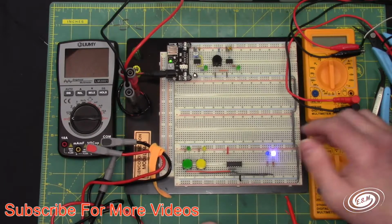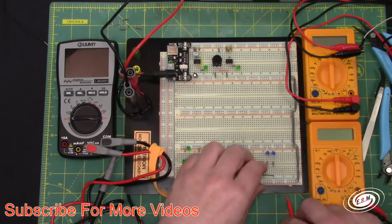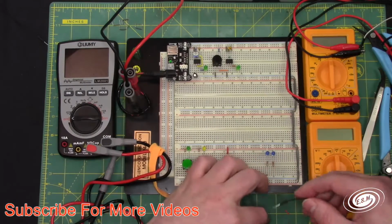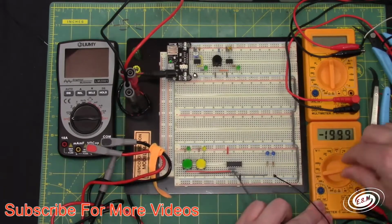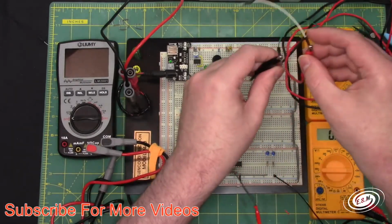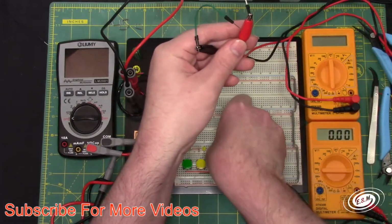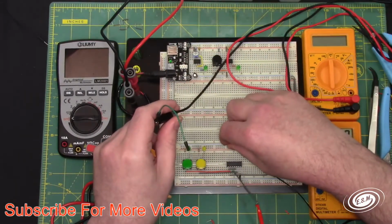So let's turn off the circuit and pull out this lead here and hook this up like this. So we've got positive flowing through the amp meter, I'm going to go to 20 milliamps, and then I'm going to take this one and pull out my power jumper, which I made jumpers so you guys could see the colors.